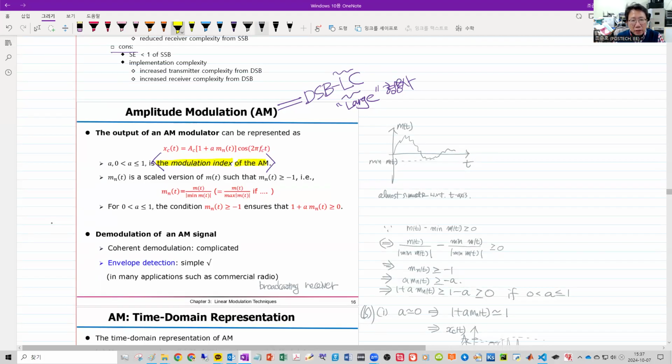And here goes the transmitted signal. So this is the real bandpass signal that models the signal applied to your transmit antenna. Got it? So you have the transmit antenna that converts the electrical signal to a radio wave. And of course, there is a power amplifier, but let's say that this signal, X_c(t), is the electrical signal applied at this point.